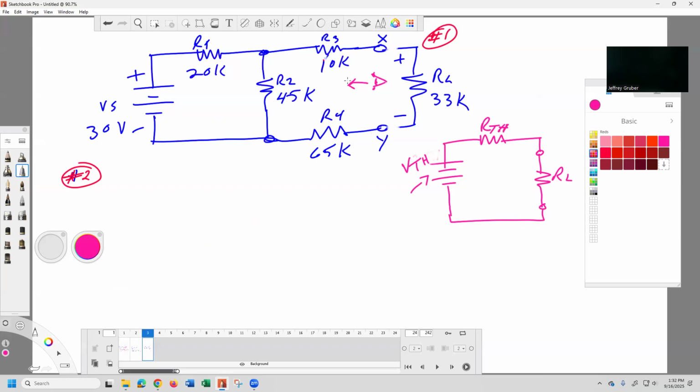This is something that bothered me when I was a student at Gateway. This voltage right here is the same as this voltage. When I was a student, I was like, yeah, but doesn't the current have to go through that resistor? It just didn't make sense. But if you think about what's inside of a voltmeter, it makes sense.